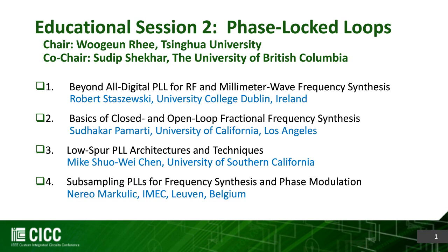And then the last one: if you build the delta sigma modulator type of PLL, doesn't matter if it's analog or digital, if you just do Dither, that will be easier, because you're basically building on your existing fractional dividers and you try to randomize it. But know that whatever you do, there's always a cost, right? Because in that case, you can increase the noise of that modulator, and sometimes people would also need to use an additional cancellation loop to take care of that noise. So in the end, I think it's just a trade-off, and it really depends on your target application.